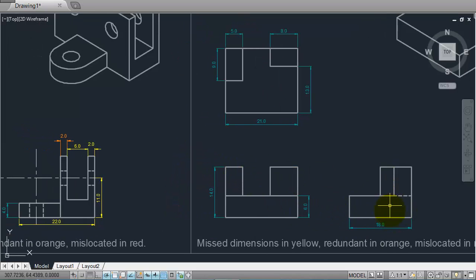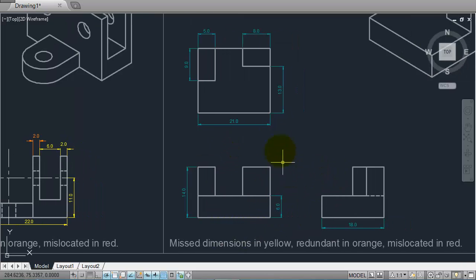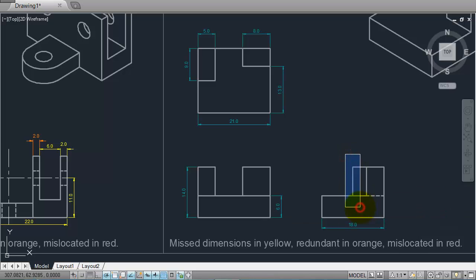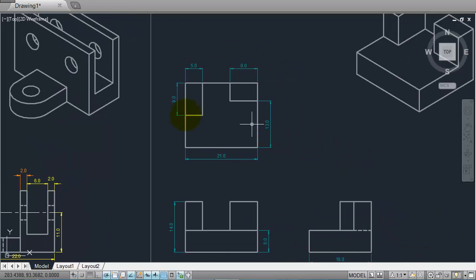Okay, so we have a total height, we have a height to this midsection, and we have a lower height. So I provided the height to the midsection, I provided the total height. That's everything I need in that direction. For the depth of the beam, I have the overall width, which is provided. I have the length to this section, which is identified by this dimension here. I have the length to this section here, which is provided by that dimension. And so everything in the y-axis, for lack of a better term, is also defined.